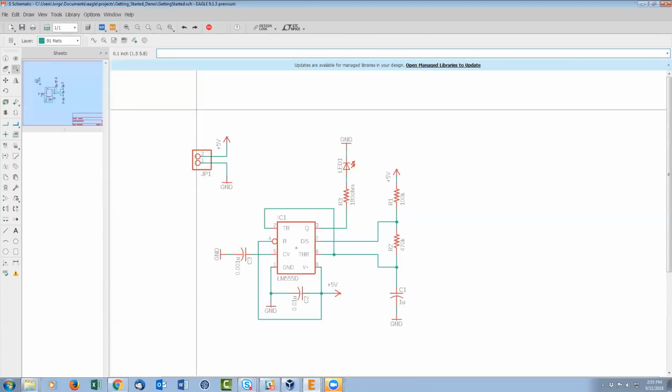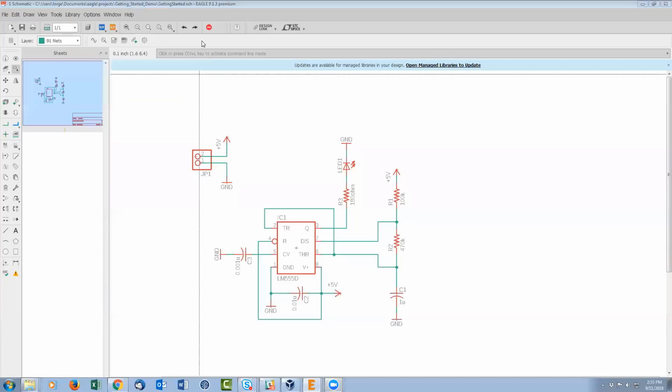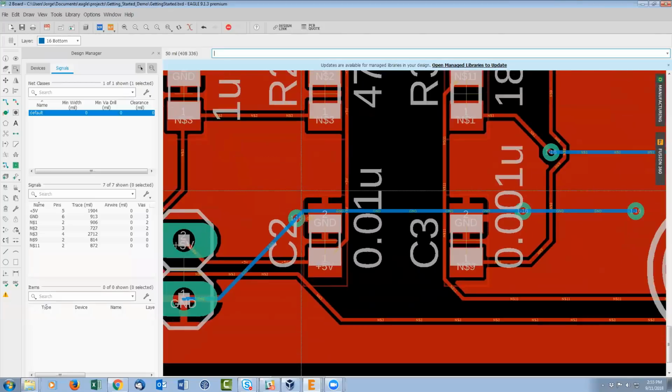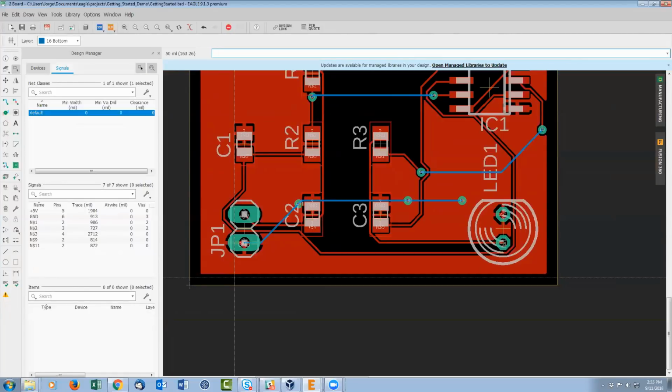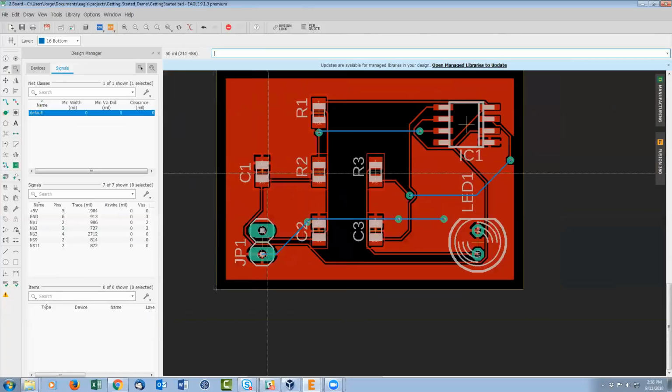Okay, now also somebody's asking, Ken is asking, how did you remove the values on the silk screen, Jorge? So if you want to remove the values on the silk screen, you just turn off T values and B values. T for top, B for bottom. By default, they are not included in the Gerber set. So you don't have to worry about them going into manufacturing data. But if you don't want to see them, you just turn off T values and B values. Yeah, so we basically do everything by layers, so we enable or disable the layers accordingly. And the same thing can be done when you're generating your manufacturing data.